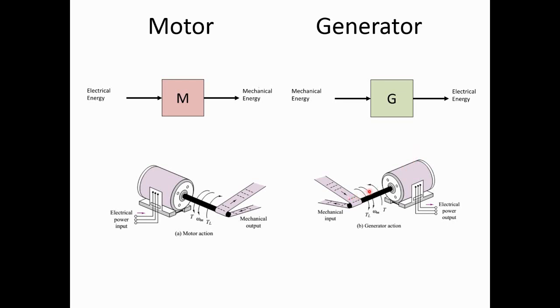So for example, in a Pasar Malam's generator set, gen set, what you have is the rotation provided by a small engine, and the engine is rotating the shaft, and the shaft will rotate the armature inside the machine, and interacting with the magnetic field from the stator will produce a certain output of electrical current, right?